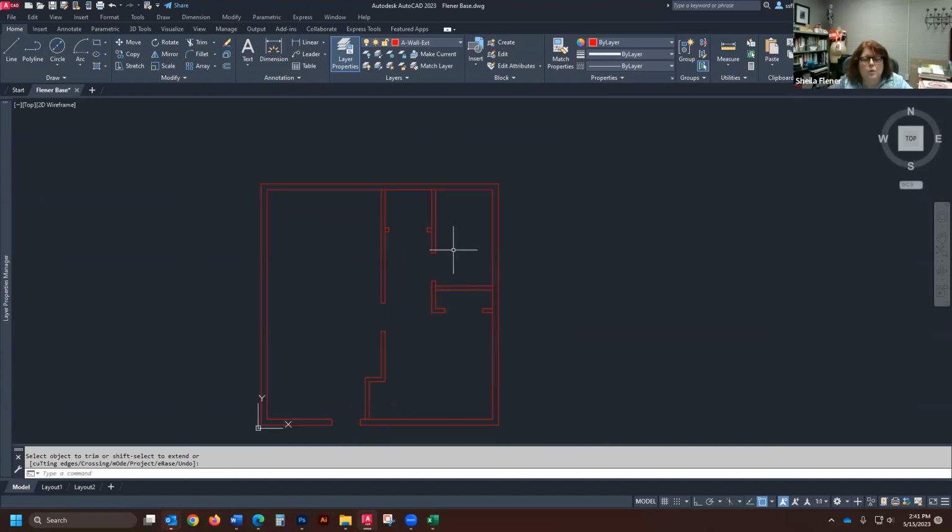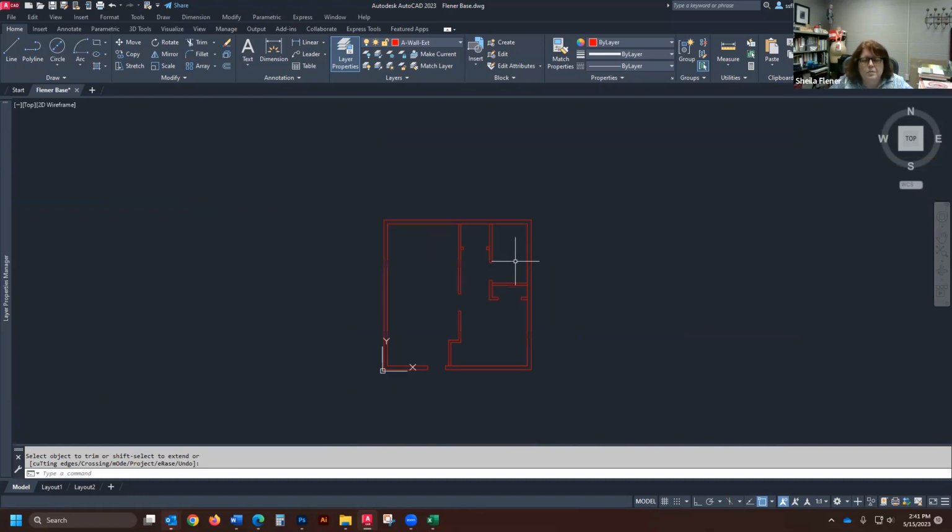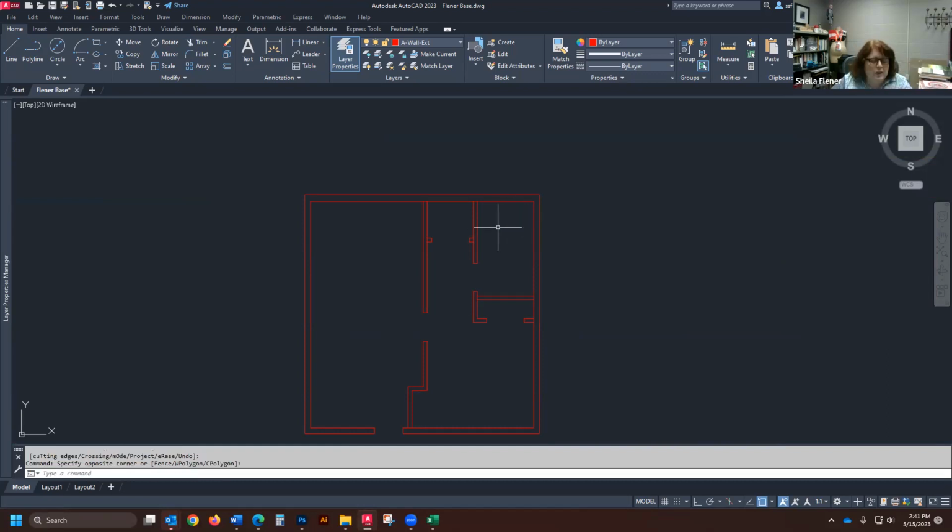We are now going to first go in, and wherever we have a wall, well, let's first put the walls in the correct layer. So all of these interior walls, remember, offset creates a copy of the parent. If we click on them without putting any commands, so you're going to hit escape and you're going to click on all of these lines.